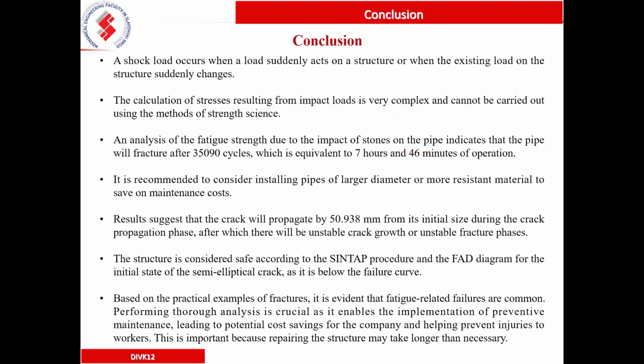So at the end, just a few conclusions. I hope I'm on time. Yes, we found that in the worst scenario, the pipe diverter will be practically broken very, very soon. It means within 8 hours. Fortunately, in practice, it is a little bit more. So this is the reason we replaced the S355 with Hardox 450 material. It is much better.